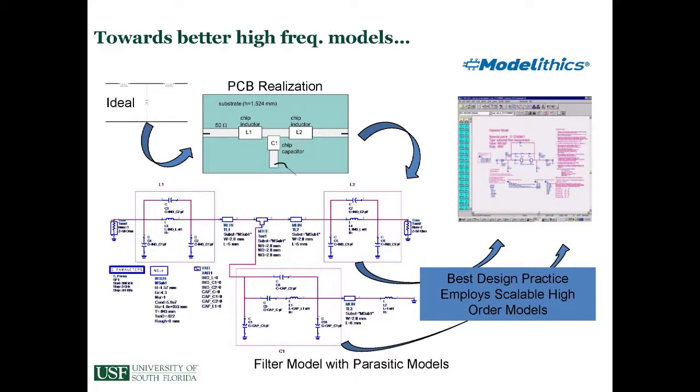All right. So at our company, which is a spin out of the university, we've been in business over the last 14 years, and we've developed models for over 200 RF component families, RLC component families. These models scale with the part value. They're much more complex versions of the simple models that I described. They model multiple higher order self-resonances, and they take into account the board effect. That is, when you place a component on a PCB board, it actually will alter its behavior.